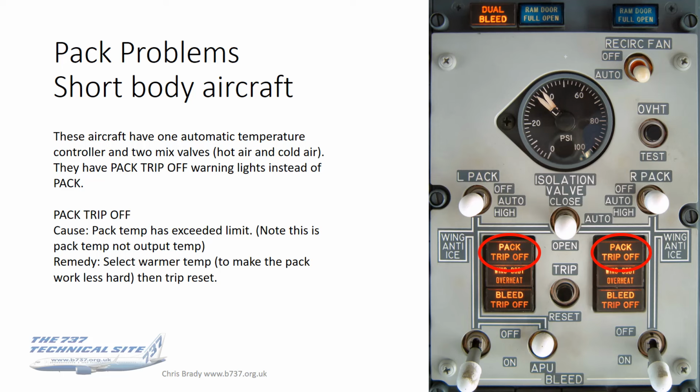But it's worth saying that this temperature is the pack temperature, not the output temperature. It's quite different. The pack temperature is a function of how hard the pack is working, and the packs work hardest when they are cooling. So actually, if the output temperature is very low, the pack temperature is likely to be very high.